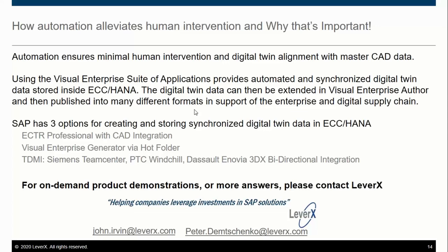Now, with respect to Visual Manufacturing Planner, the user would also like to know how non-geometric components are handled. Well, when you create that routing, there's a menu icon in there that will let you insert any non-geometric component that you need in your BOM, and it still gets added to your BOM. And yes, you started off looking at a CAD structure, but this visual manufacturing planning tool saves the SAP business object bill of materials as well. So when I told you I started with a CAD structure, I took the EBOM and the CAD structure, and I created the MBOM as an SAP business object bill of material.